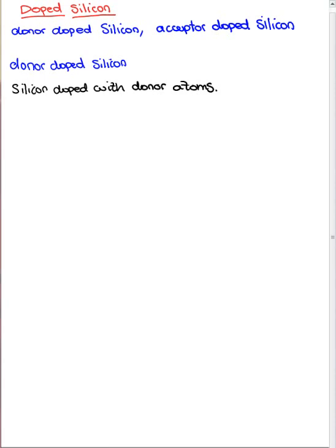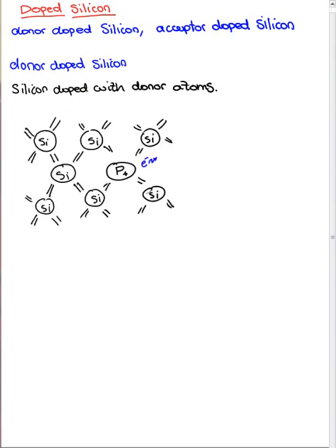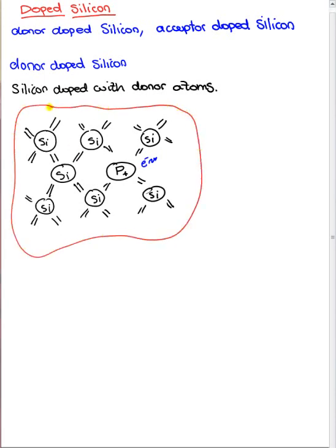So now you have what's called a free carrier, right? In this case, an electron. So what you have is the following figure. Here's the lattice, but now we have added a phosphorus atom, right? Once we do that, phosphorus has that extra electron that comes out. So now phosphorus is not neutral anymore, but becomes positively charged, the atom itself, since it lost an electron, right? So you got a positive fixed charge because this atom cannot move, and we got an electron that can move freely around the lattice, right?